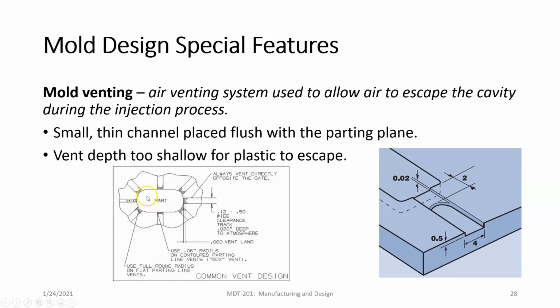So whenever you fill something, think of this as an area that you're going to fill with the plastic. This is where the part is. Right now, it's already filled. And it's filled with what? It's filled with air. So if we just squirt this plastic in here and the mold halves are tight together, we're going to be pushing against this air volume that we're not going to be able to push against, right? So the air is going to keep out the plastic.